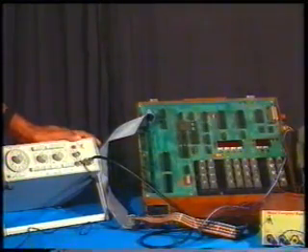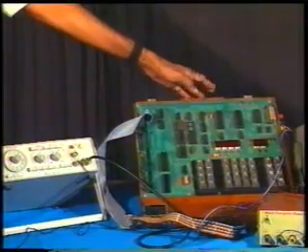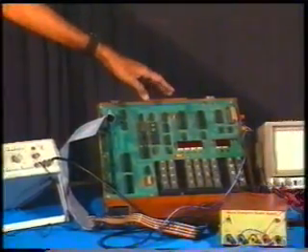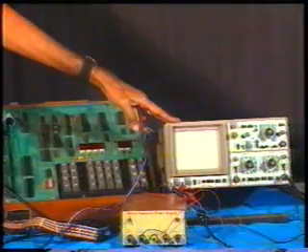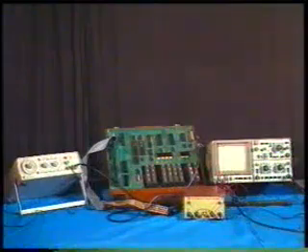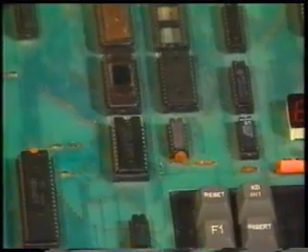Friends, we had seen the description of modes 0, 1, 2 and 3. Now we will view a demonstration which implements mode 3. The clock output of the function generator is given as the clock input to the 8253 of the microprocessor trainer kit. The output of 8253 is connected to the oscilloscope. The clock input is also connected to another channel of the oscilloscope so that clock and output of 8253 can be viewed simultaneously. The counter 2 of 8253 is set for mode 3 and BCD count.